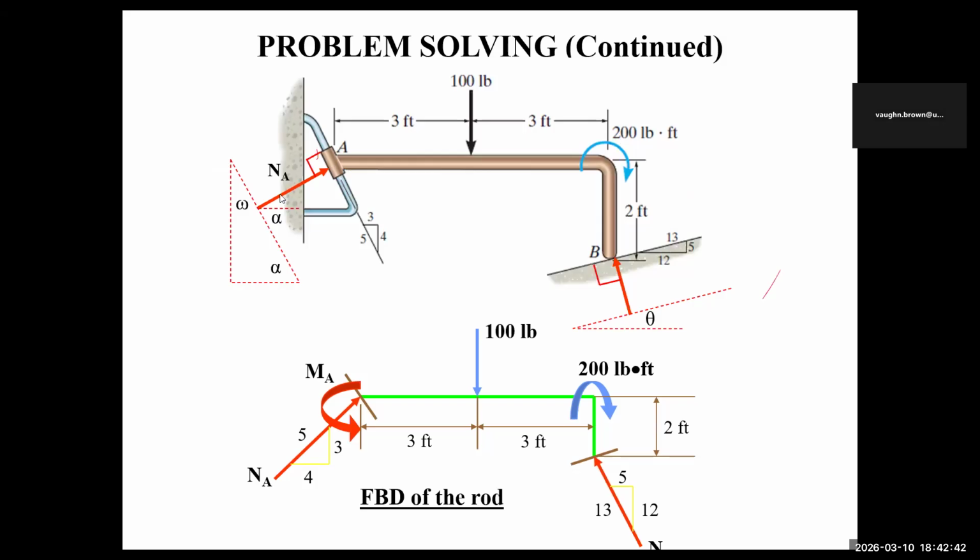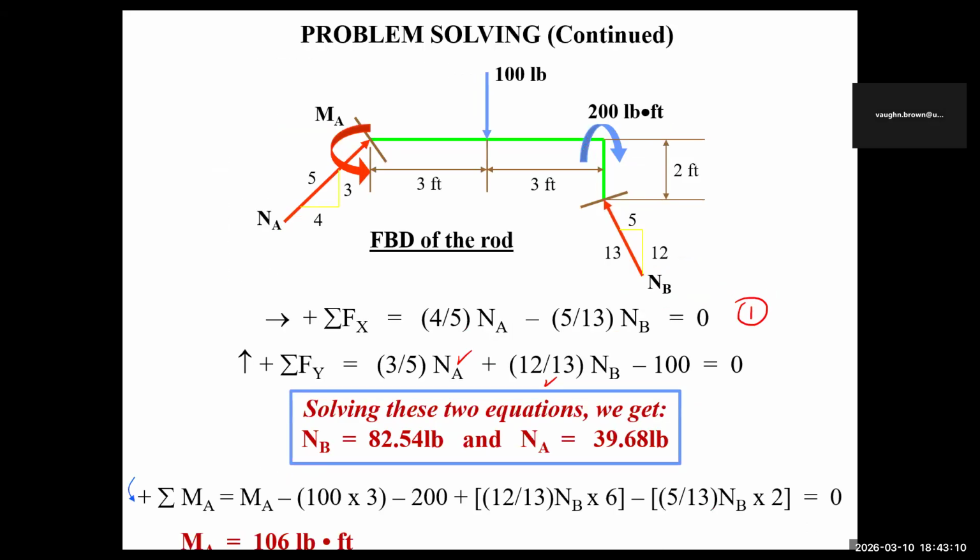This is a collar, so it will just have one reaction here, simple. And then this is another point here that's resting on the rod, so another perpendicular. So they all are at right angles to these here, right? So you can quickly see it, and you can see how they came about to this. If you have this triangle across here, then these are alternate angles here. So that is alpha, and then you can simply work it out. So you can look at that in your own time.